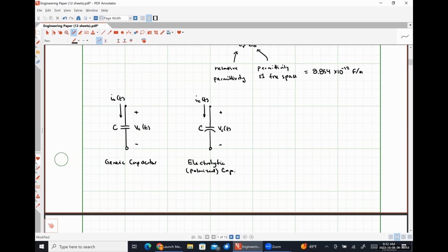You may see these two symbols used interchangeably, but that's technically not correct. An electrolytic capacitor has a very specific positive polarity terminal and a very specific negative polarity terminal. If you do not connect things correctly, it will literally burst. How many of you have ever had a piece of electronics stop working, and you open it up because you smell something funny, and you see that one of those cylindrical looking things has its top kind of domed over? Nobody takes enough of their stuff apart anymore, apparently.